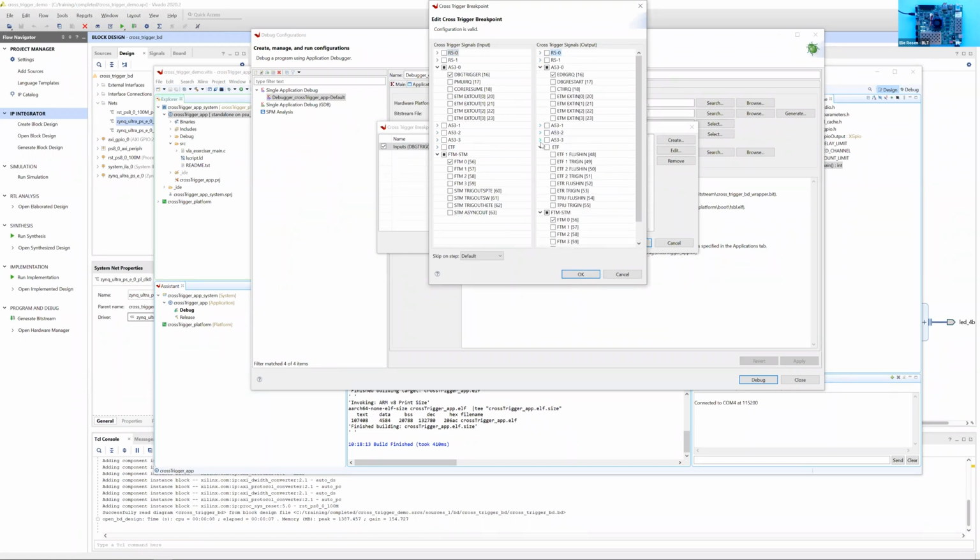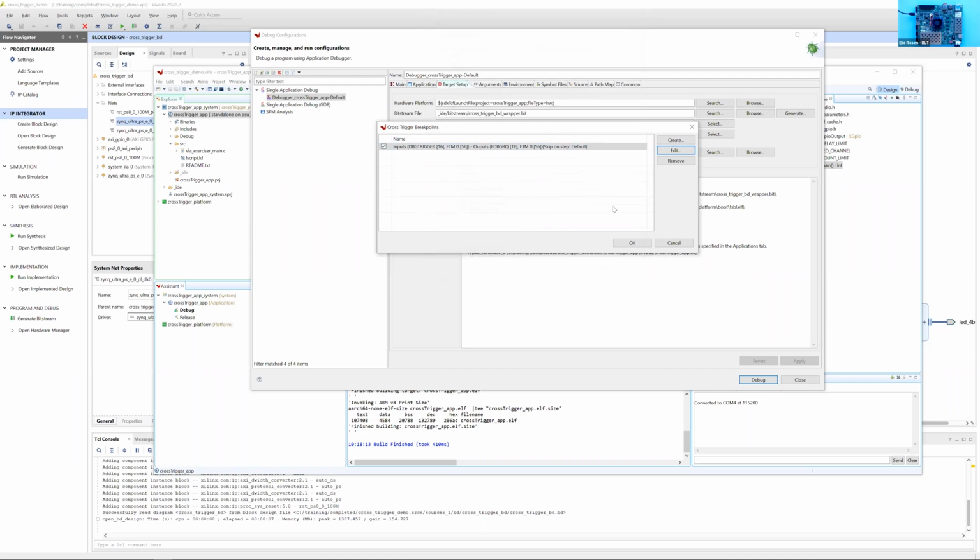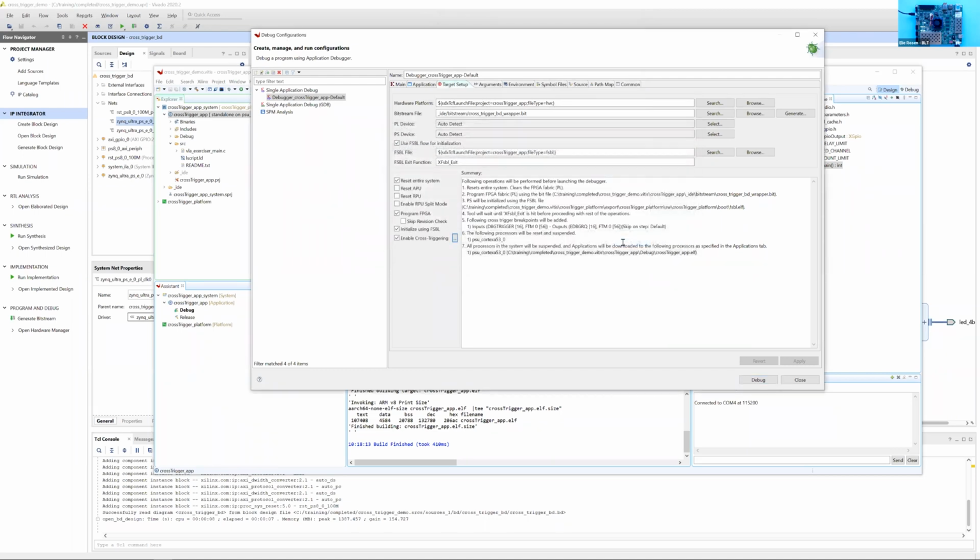There are 4 ports that we want to turn on. So the first one is the input side for the cross trigger. On the A53, we're going to enable this debug trigger port. On the acknowledge side, we're going to turn on this fabric trace module system trace macro cell connection, FTM0. Then for the output, if I hit a breakpoint, it will send out a signal over the external debug requests interface. And then it will also, on the FTM0, be able to receive that acknowledgement coming back. All right, so with those specified, I will now be able to cross-trigger on my software.